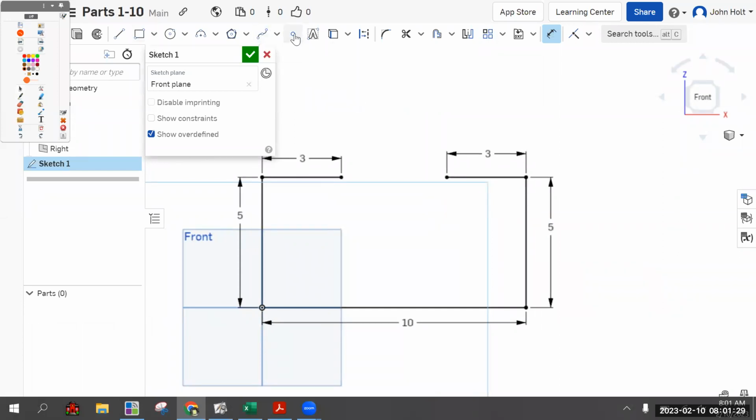Okay, so yeah, let's get it. You can do this with the kind of, I don't want to say cheating way, but the sloppy way would be to make a line, find the exact center point, and then dimension that to 2. But that can actually mess you up when you're trying to do lofts. Lofts are very particular with where lines are.